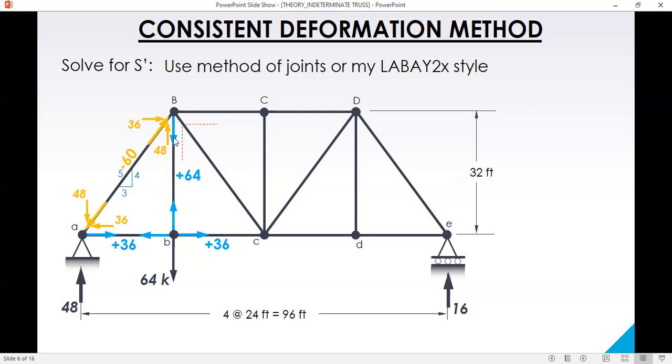Okay. Next, for diagonal member BC, we have components again. Now, since this is 64, then this component must be equal to 16 upward so that the sum of the vertical forces becomes 0. 48 upward, 64 downward. Kulang og 16 upward. So this component must be upward. The value is 16. So if we check the vertical forces, it's already equal to 0.